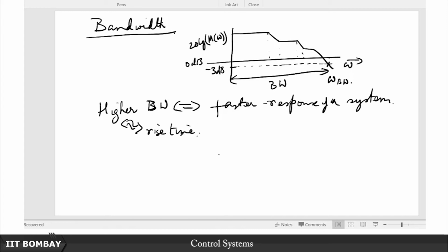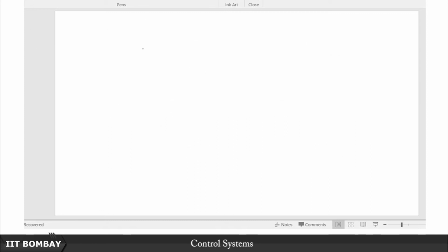So here, if you would permit me, I would do a bit of hand waving, and I would just focus on the so-called second order system. So suppose you have a second order transfer function like this, the underdamped case for example. We know the asymptotic approximation of this, and we are not really interested in drawing the resonant peak accurately here.